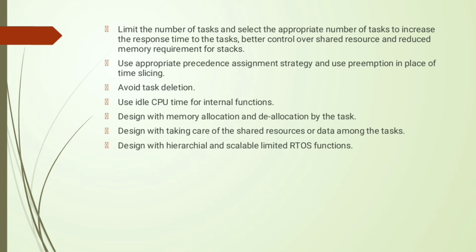That is, we need to reduce the number of tasks, and also we need to reduce the number of functions. That is, we need to include only the necessary functions inside the task. That is for increasing the response time. And also we need to have better control over the shared resource as well as the memory for the stack.